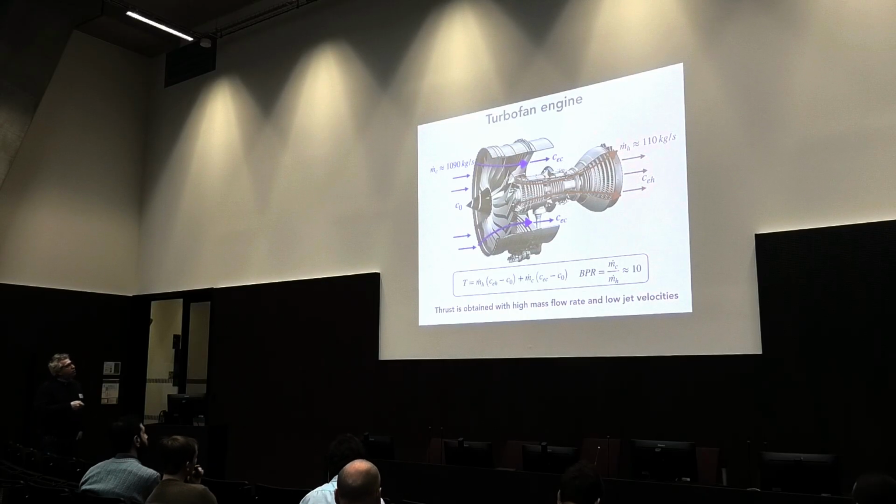So this is the job of this huge fan, this huge ventilator that will draw a huge quantity of air each second. And you split this flow into a cold flow in blue and a hot flow in red. So the hot flow is passing through the engine that I just showed you 2 minutes ago, and the cold flow is bypassed. And so the role of this big ventilator is to accelerate, but by a very small amount, the cold air, but a large amount of air.